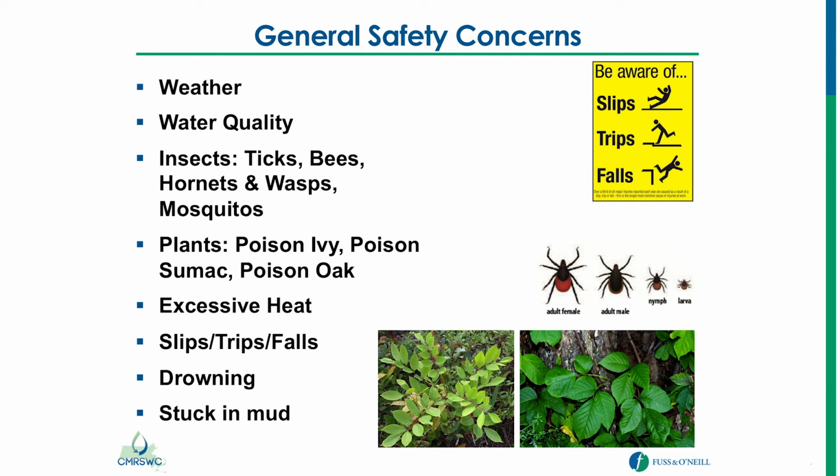Some safety concerns that you might have in the field, as I was mentioning before, water quality. You are looking for potential raw sewage. Ticks, bees, hornets, wasps, mosquitoes, deer ticks especially. If you're walking through the forest or woods, wear light colored clothing. You're going to get ticks on you. It's going to be part of the plan, unfortunately. Poison ivy, there's a ton of it out here. When you're walking around, if anybody doesn't know what it looks like, let me know, I'll show you. I found out last Wednesday the effects of poison ivy. You can probably see it on my eye.